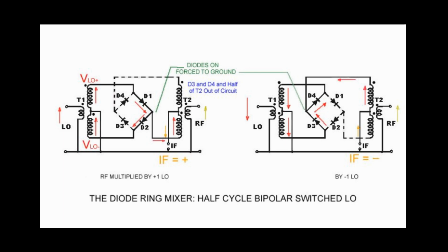Now we know those turned on diodes don't represent a perfect 100 ohms each, or 200 ohms, giving us a 1-to-1 SWR. So don't expect to have a very good match on the LO port. It's another reason why we like to put attenuators on these ports. These diodes don't look like anything like 50 ohms, that's for sure. They're pretty complex impedances.